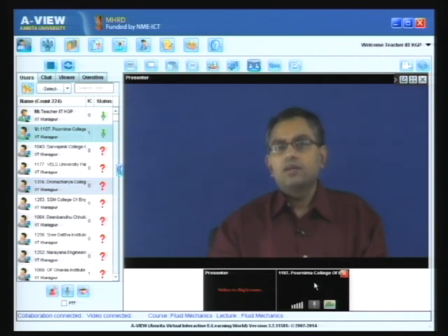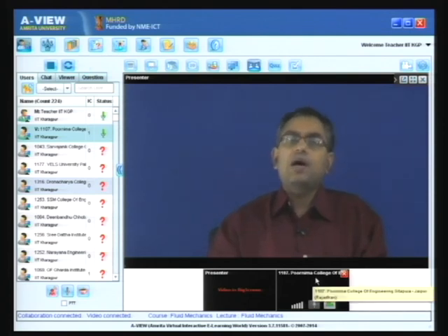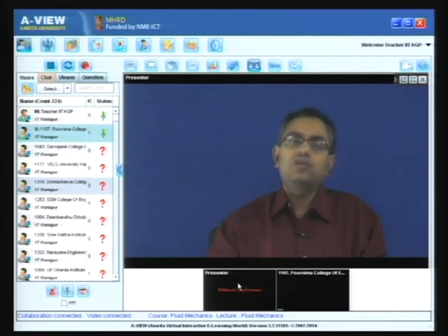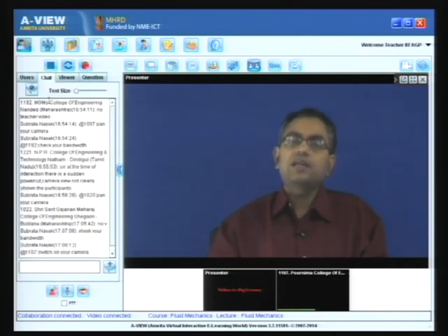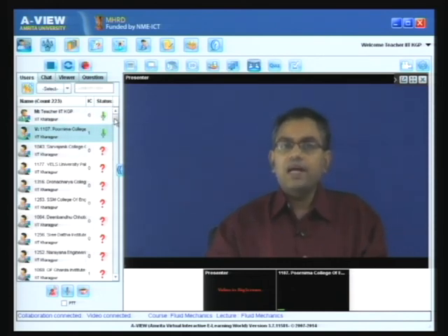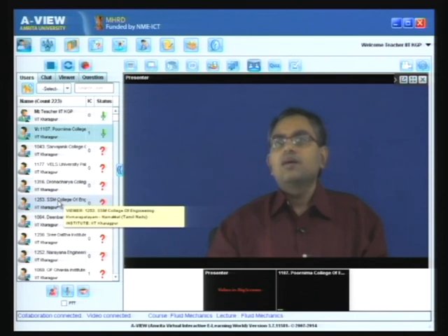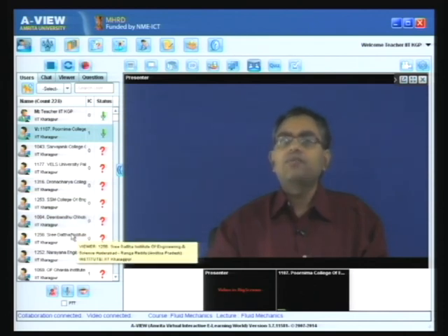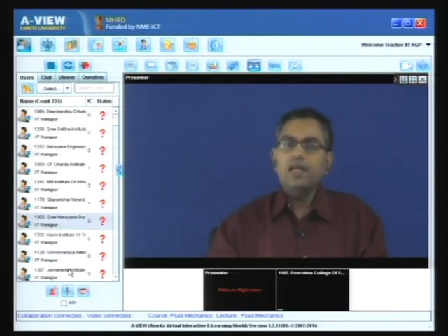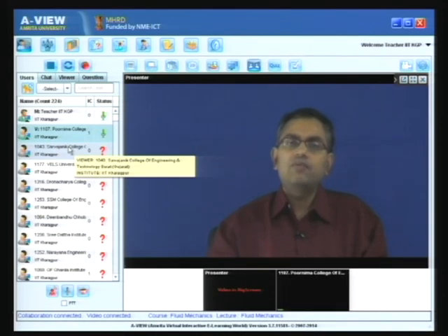For both laminar and turbulent boundary layer thickness. What is the boundary layer? Typically, boundary layer thickness is infinity. If you ask a mathematician, a mathematician will say that the boundary layer extends up to infinity. As engineers, we know that there is a finite region which we call infinity. What is that region? That region is where the velocity is roughly 99% of the free stream velocity. So, 99% is as good as if you have reached the free stream.